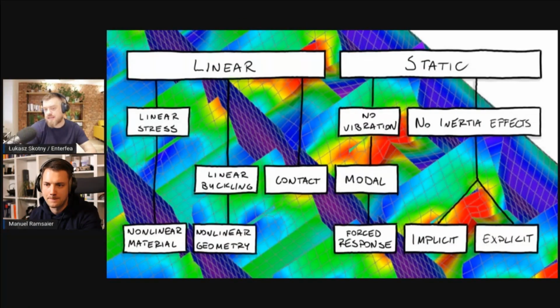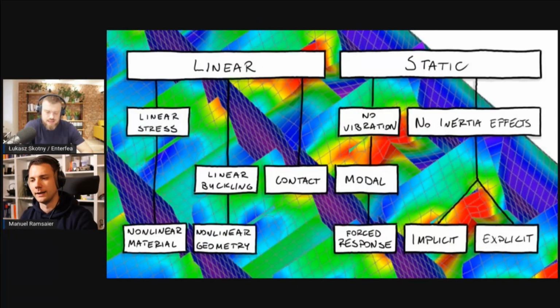To this end, I think the difference between modal analysis and force response would be something like this. Let's say that I have a machine that has 4 hertz of load frequency. Yes. And the first mode of my structure is 3 hertz and the second is 5 hertz. So clearly my machine is somewhere in between the first and the second mode. Yeah, the numbers are crazy. This will never happen in real life. Those things are way closer together.